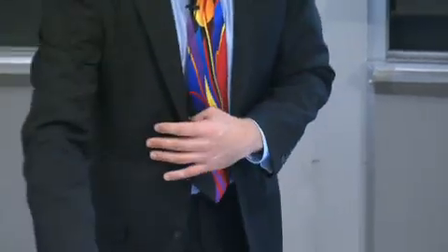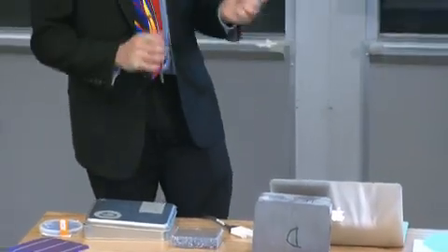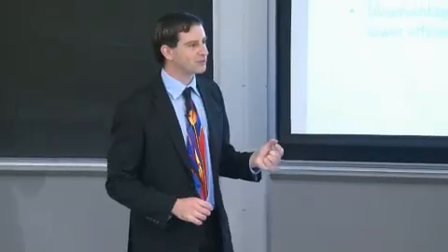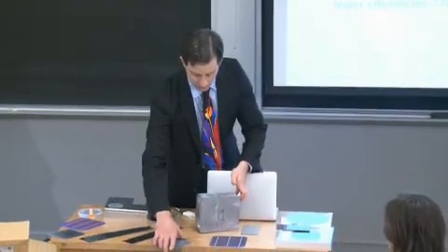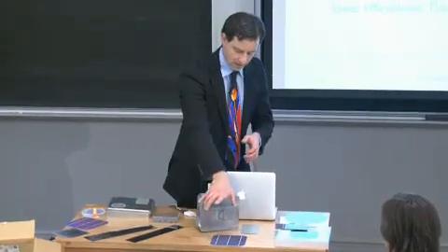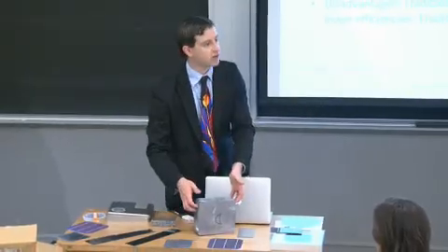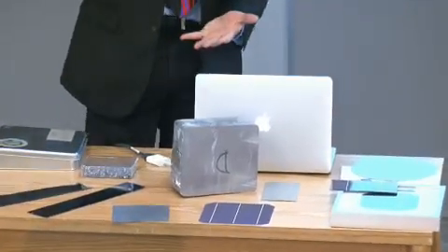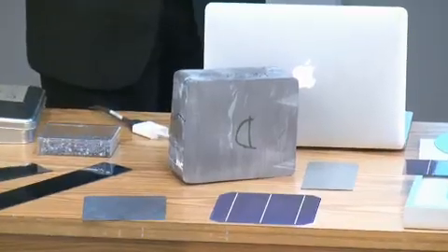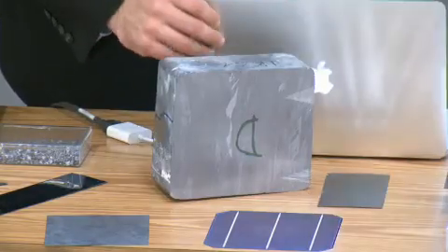resulting in more defect-rich materials. So one group decided, gee, the embedded cost in the wafer is just so large that we have to make it thinner. And we have to avoid using these ingots, like this one right here, from which these wafers are sawn, right? So your wafers are sawn out of the ingot like this, as shown. During the process, about 50% of the silicon is lost to sawdust. And they said, well, let's develop a better way. Let's extrude the wafers directly out of liquid molten silicon and make ribbons of silicon instead. That way we don't have the sawdust and we don't have to have this expensive ingot solidification step.